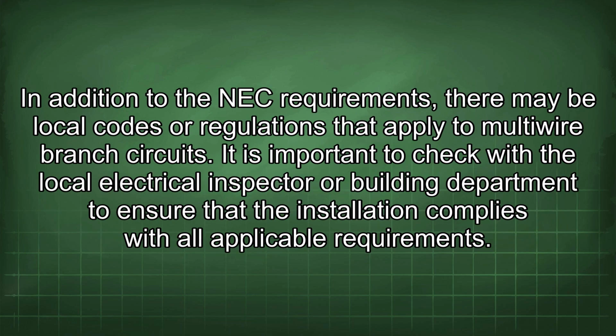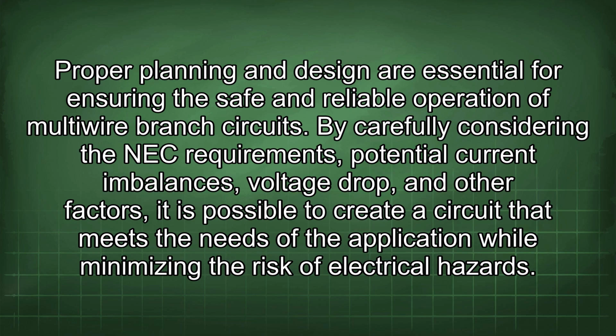In addition to the NEC requirements, there may be local codes or regulations that apply to multi-wire branch circuits. It is important to check with the local electrical inspector or building department to ensure that the installation complies with all applicable requirements. Proper planning and design are essential for ensuring the safe and reliable operation of multi-wire branch circuits. By carefully considering the NEC requirements, potential current imbalances, voltage drop, and other factors, it is possible to create a circuit that meets the needs of the application while minimizing the risk of electrical hazards.